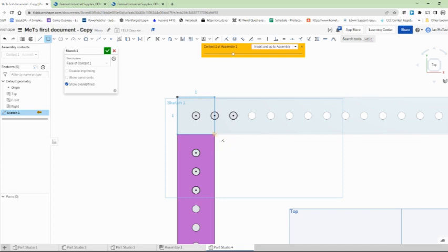Now you'll notice I'm holding my mouse over that point and then moving, and I get that dotted orange line. And that little icon indicating that the end of this point is horizontal to that. Perfect. Click that. That gives me some black lines because they're constrained based on that point and being horizontal to that point. And the blue I can move around, which I'm going to change in a moment.